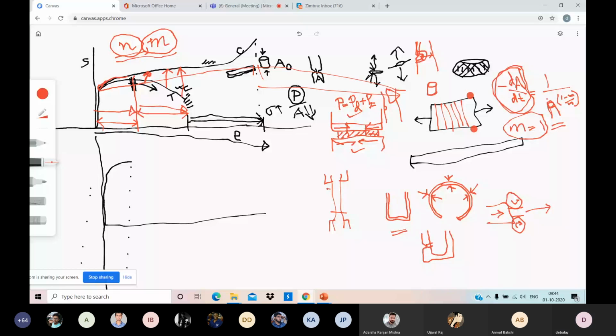There is no resistance this side or that side. But in compression, if it has to flow, it has to overcome the friction. So in compression processes, you need to apply proper lubricant: molten glass, Teflon, graphite, a lubricant that survives at high temperature.